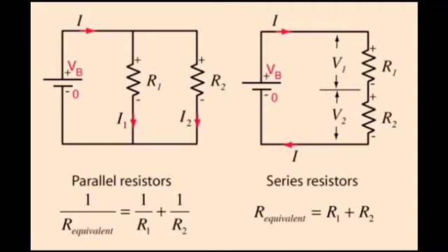In the second figure you can see the series arrangement of the resistors, where current flows in a linear way and the potential difference is different for the different resistors. Similarly, to find the equivalent resistance we add the resistors, the values of resistance, in a linear way.